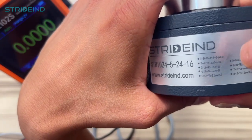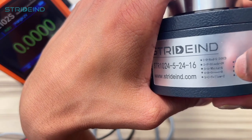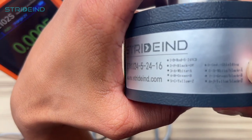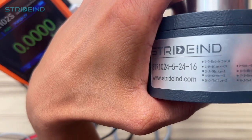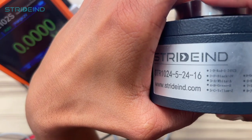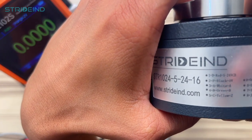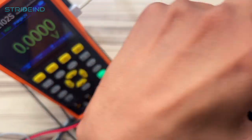Then you have three types of output, A, B and C, and all of them have inverted pulses. So A has A negative, B has B negative and C has C negative. We'll see how we can work with them and troubleshoot them for the functionality of the encoder.